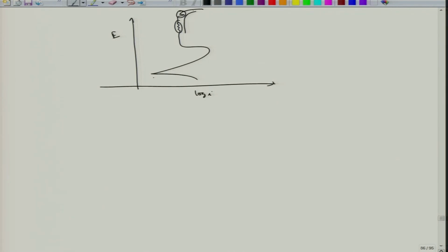So, there are techniques called potentiostatic technique, and cyclic potentiodynamic test, where you can sense the particular potential where I can start getting those metastable pits. Now, in this particular graph, the pit is growing and then finally the metal passivation is breaking, and that is what gives you a transpassive zone.